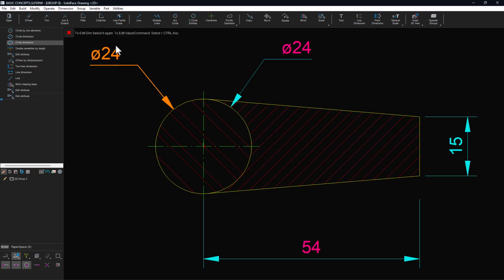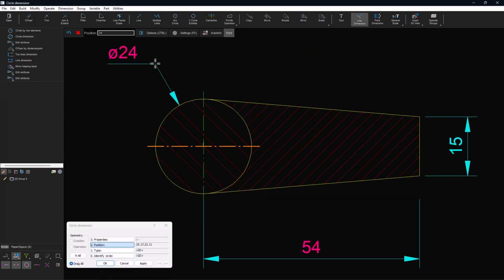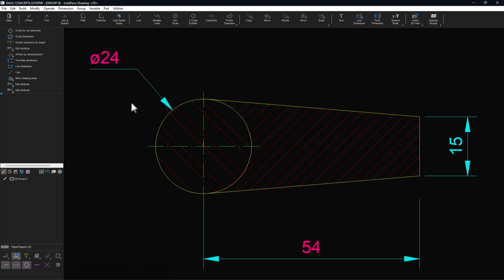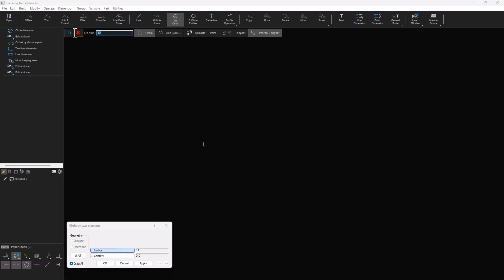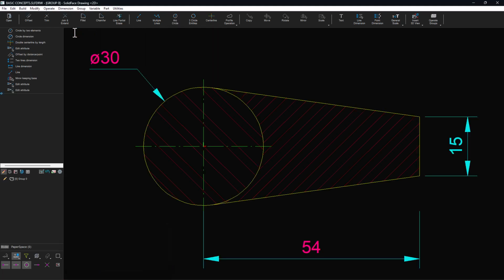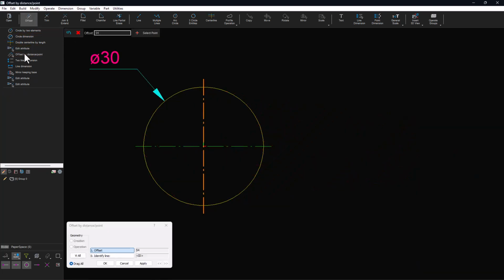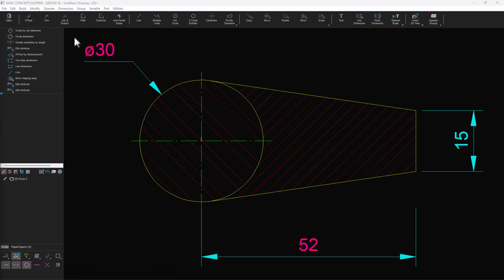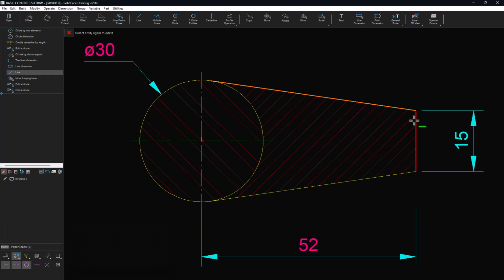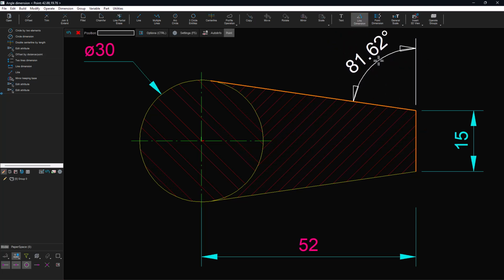Editing the dimension position. You can edit the circle directly in the list of commands. Note that if any command or geometry is modified, the fill attributes are automatically restored. Create a new angular dimension. Select the lines and choose dimension.